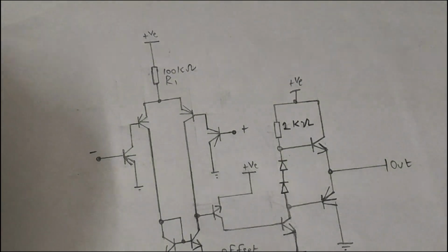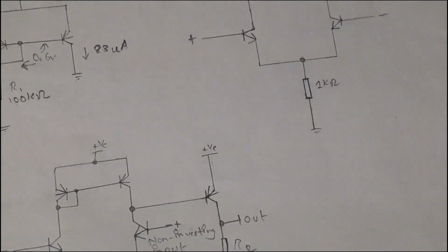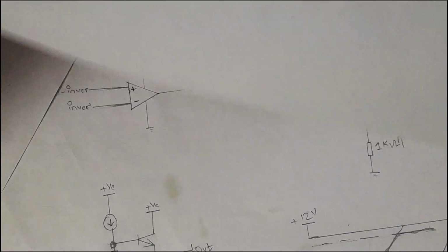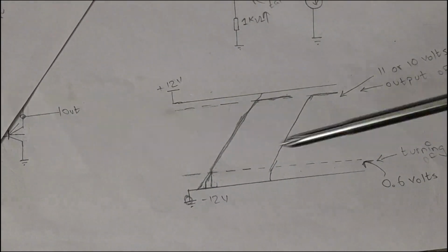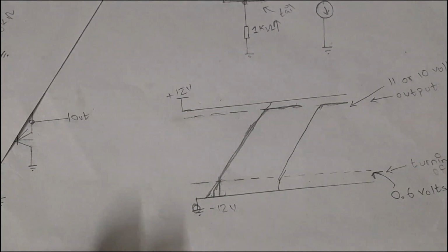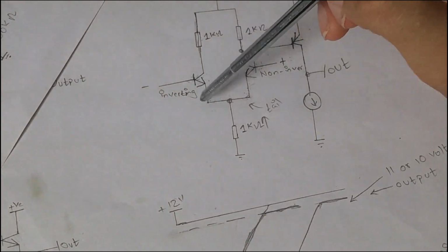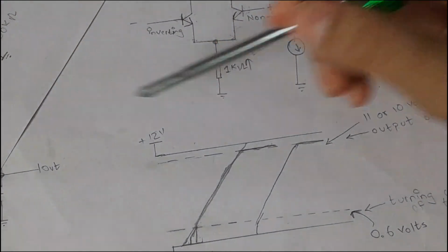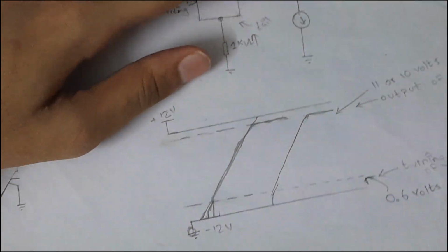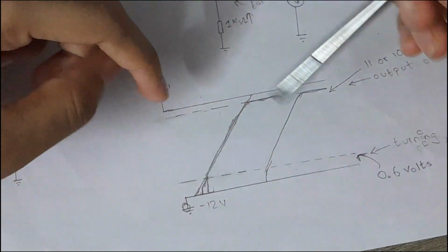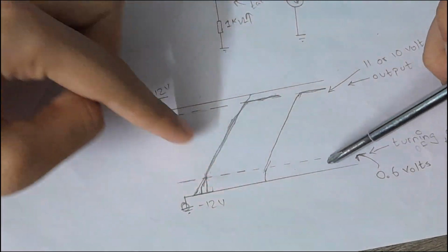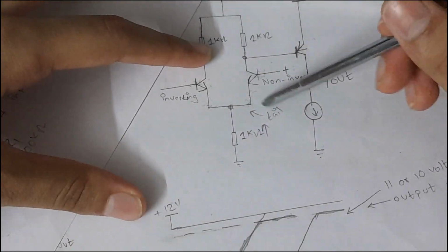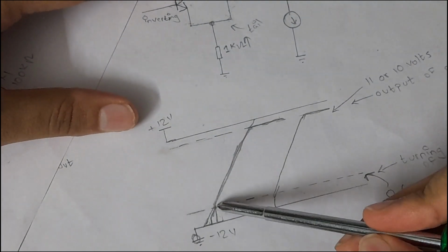But anyways, this was the video about op amps. We can also build an op amp on a breadboard, and we can also talk about the output of the op amp. The op amps are using silicon transistors which have around 0.7 volts of voltage drop between the emitter and the base. So what we are doing is that we are connecting an oscilloscope, and basically at any voltage lower than 0.6 or 0.7 volts the transistor does not conduct, so basically the output is low.